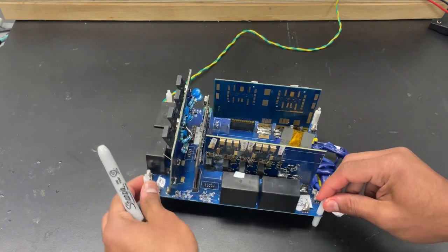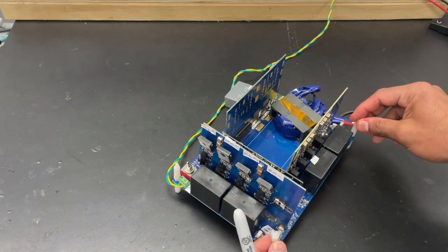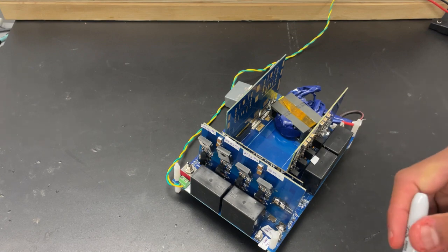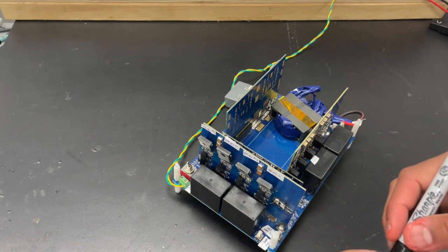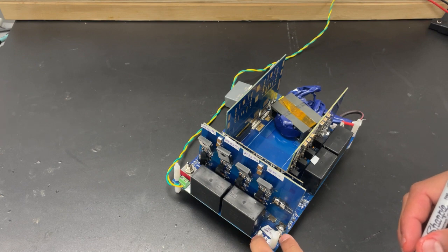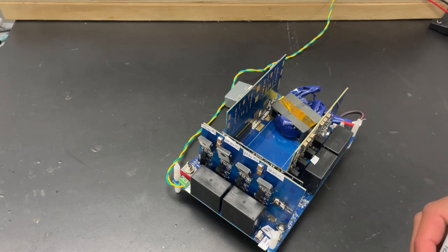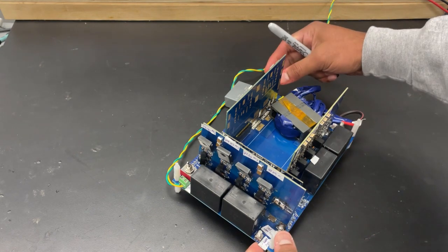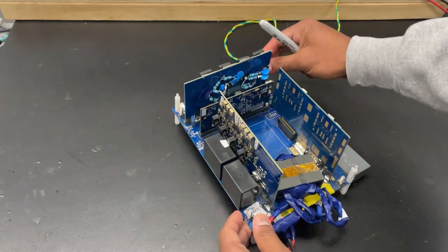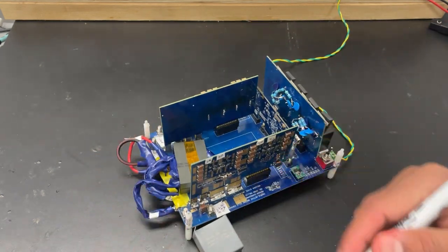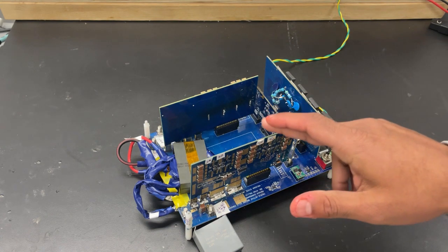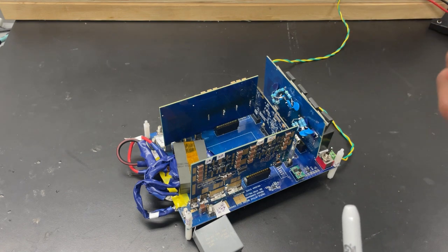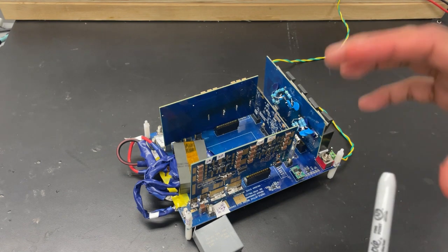Coming down to the secondary side, I'm going to align a little bit so that you can have good visibility. As we can see, we are using the GaN Transphorm cascode devices, 900 volt rated, for this particular side, and the output voltage, nominal 600 volts, has been obtained at these two terminals, and then that is connected to a load such as an HV battery. Coming down to the tertiary side, you can see that it is being realized using this particular PCB. On this we are using the EPC GaN 2020 devices, which is 60 volt rated.